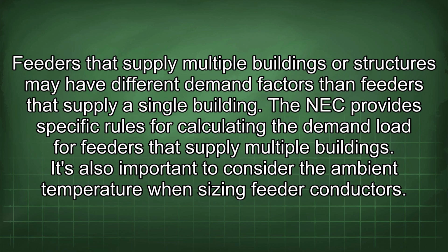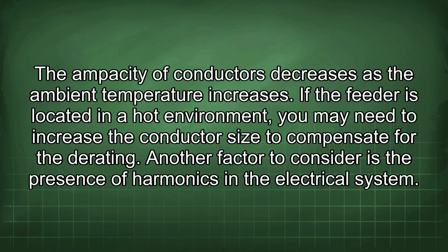It's also important to consider the ambient temperature when sizing feeder conductors. The ampacity of conductors decreases as the ambient temperature increases. If the feeder is located in a hot environment, you may need to increase the conductor size to compensate for the derating. Another factor to consider is the presence of harmonics in the electrical system.